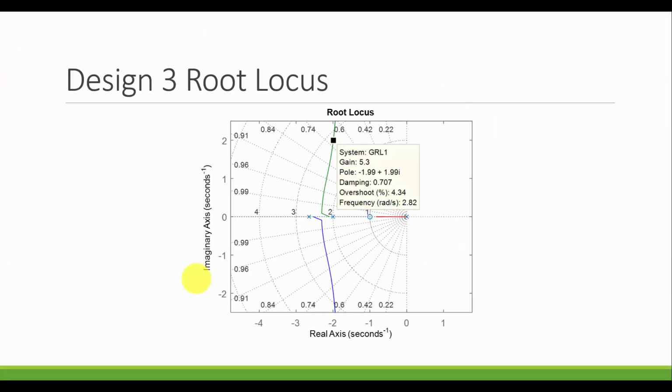So if we put this gain with these zeros into our closed loop system, we're going to find here, again, dominant poles where we desire them, and we're going to have a 0 at -1 in addition, and a third pole at -0.667. Now, I'll point out at the moment something different about this design than the second design. Both the extra pole and the extra 0 are to the right of the real part of the dominant pole. So -2 is greater than the -1, 0 that we're adding and the -0.667 pole that we're adding. So we're going to simulate this, but we're going to see some strange things when that is the case.